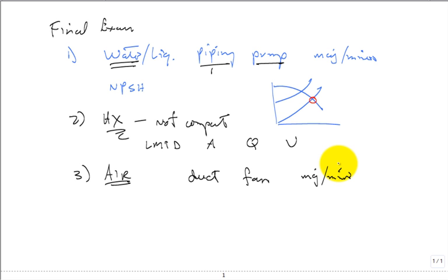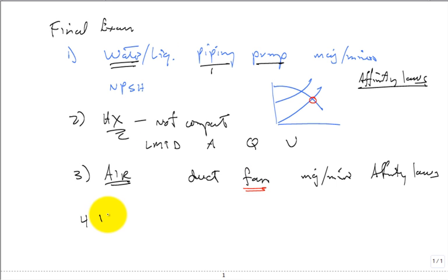So put that together with this fan. You still have your affinity laws for the pump, liquid system, the same. Affinity laws for the fans. Fans can be a little more complex because you have slightly different characteristics, especially you have forward tip blades on blower motors. And then what was the last one? Uncertainty analysis. And you can do the differentiation, or you can do the perturbation.